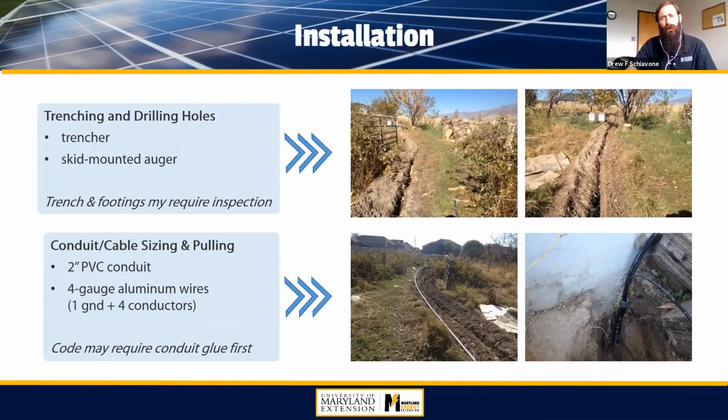But I'll say, you want to be careful, especially when you're covering that kind of ground, that you don't have voltage loss. And so as you pick out the supplies, the manufacturer will typically recommend what kind of cabling and wire to use so you don't experience significant voltage drop. Another aspect of this is those local building code and permitting issues arise.